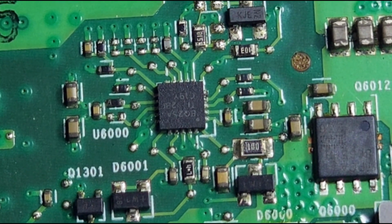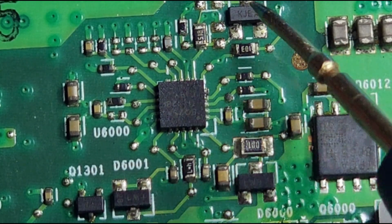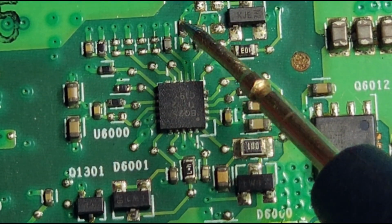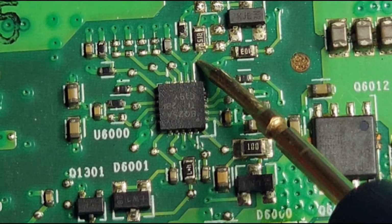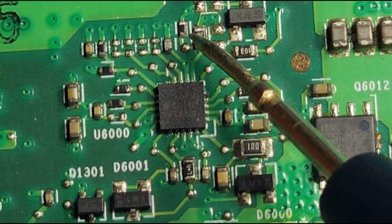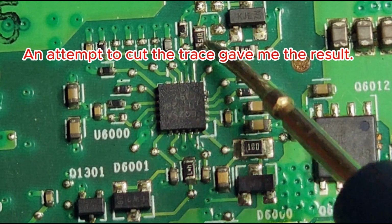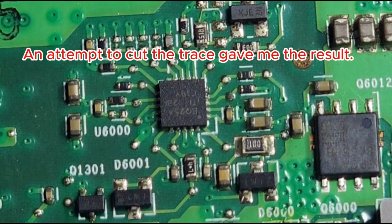Before replacing the charger IC, we can do a trick here. Here we have the trace going into the charger IC after the resistor divider. I'm going to cut this trace in order to isolate this part and this part. After cutting this trace, I can see whether we have the divided voltage on these pins. Let me take the knife.